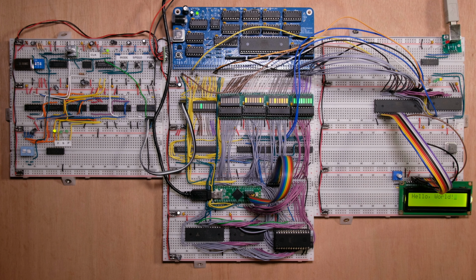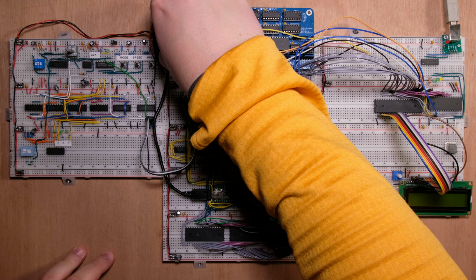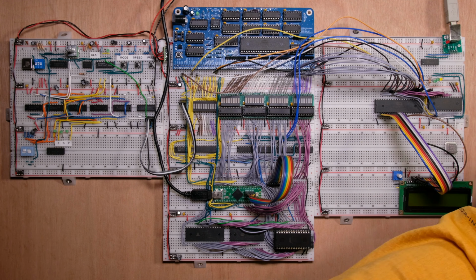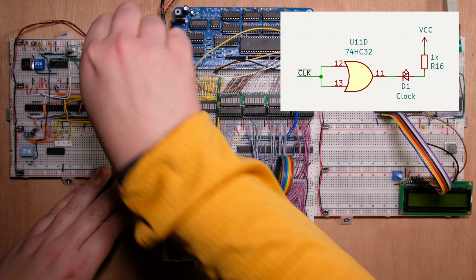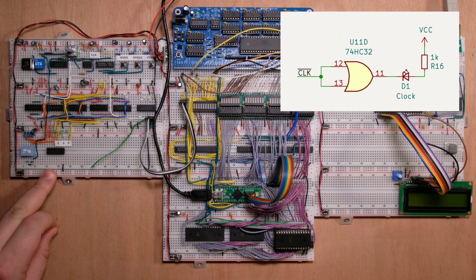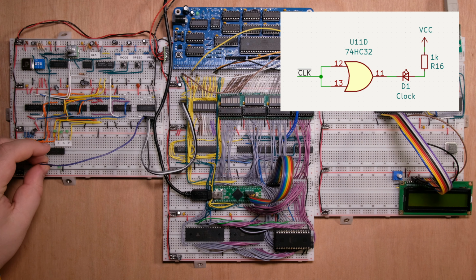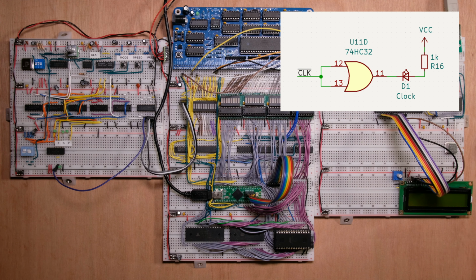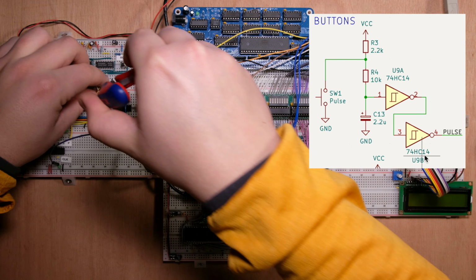So let's get started. The thing we can do is yank this oscillator. We won't need it anymore. And I can just take the one from the breakout board because this one is not in use when the debug clock is connected. Now we need to move the clock LED to the OR gate. And by the way, I'm just realizing I haven't pulled up the unused inputs here. I'm going to use a temporary connection because we're going to rewire the middle section in a minute. And there we go. And we can use the newly free inverter to invert the pulse clock.